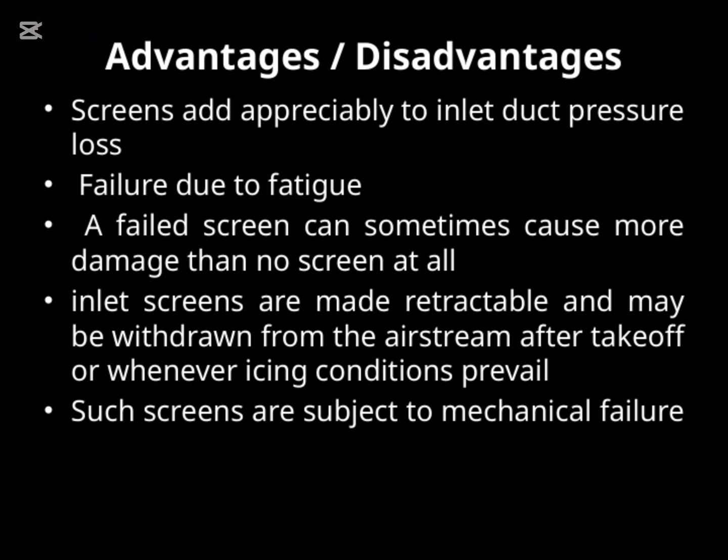One key point to remember is that screens do add to the inlet duct pressure loss, which can slightly reduce engine efficiency. While they serve an important protective role, they can also fail due to fatigue over time, especially after repeated cycles. It's crucial to understand that a failed screen can sometimes do more harm than good. If it breaks apart, debris can enter the engine and cause damage.